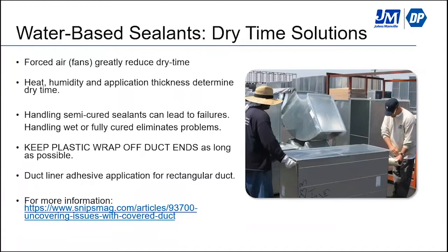Essentially, shops are fabricating duct with sealed seams with water-based sealant and water-based duct liner adhesive to adhere the duct liner. It has created moisture and curing problems because the water has nowhere to evaporate. I have solutions and different strategies for eliminating this problem. Again, the website is there for those who are interested.